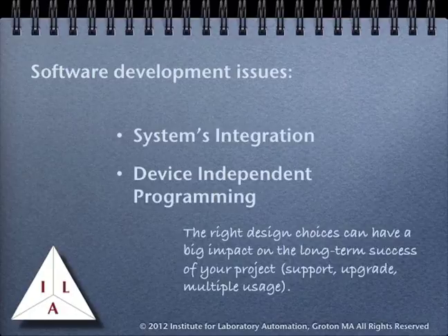One way to approach the problem of integration with instruments that are not included in the vendor's product set is to use device-independent programming. This is a technique that is widely used successfully in the graphics industry as well as other applications. The idea is to confine all device-specific functions to a small number of subroutines so that any changes in the devices can have minimal impact on programming. In short, instead of scattering the device-dependent code throughout your program, it's localized, and as a result can minimize the impact of changes. Since equipment changes over time are common, planning can have a significant effect on the long-term support and the ability to upgrade and maintain systems.